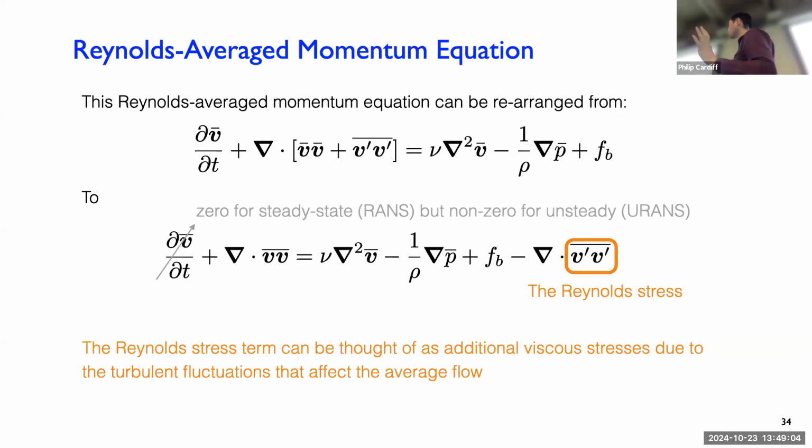Turbulence modeling, the whole area, is just about how we can calculate this term without doing DNS. That's essentially it. We'll talk about one approach to do that, using k-epsilon, which you use in the lab, but I'll leave that to the next step. Okay, thanks.